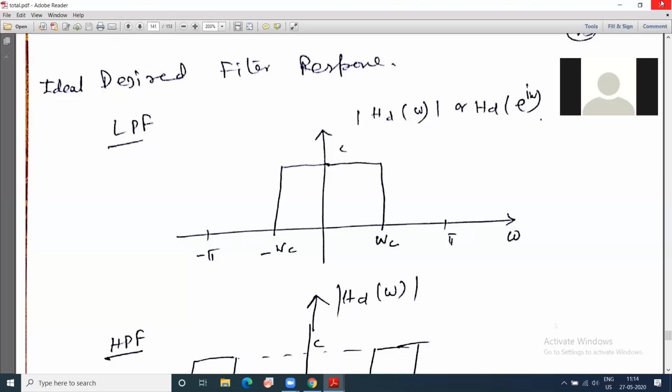Okay sir. Now, step 6: obtain the discrete time Fourier transformation of h of n to obtain the frequency response of the filter over 0 to pi, because minus pi to pi is the range I have fixed.